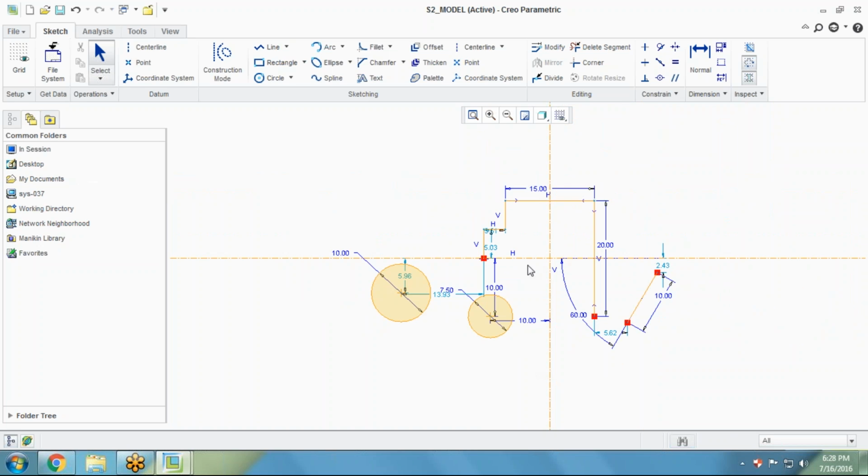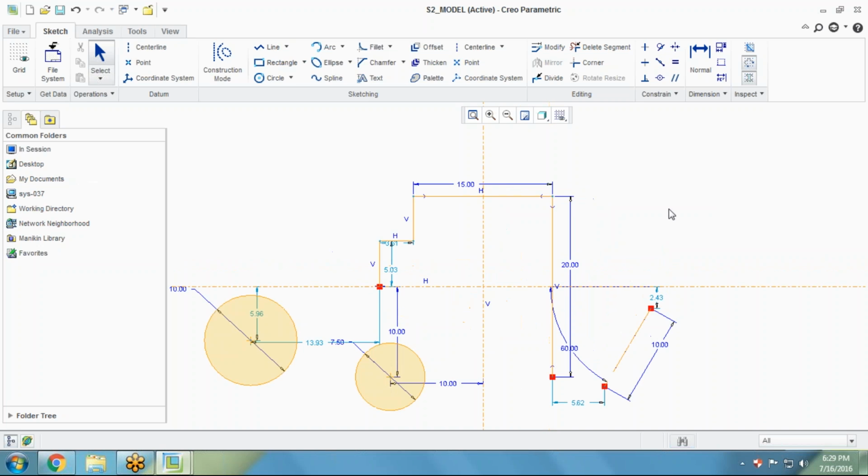There will be very complicated areas when we have a number of objects here, and at the same time dimensions will also be populated, the weak dimensions. But whenever we are creating, we cannot delete the weak dimensions. We can create some positive and adaptable dimensions instead of them, and then the weak dimension will be removed automatically.